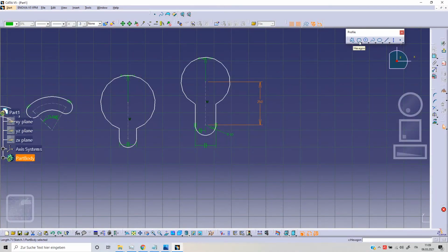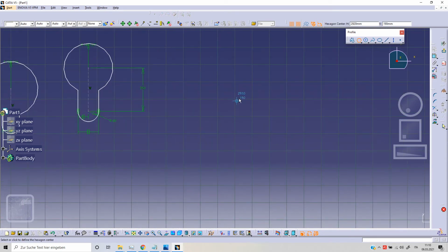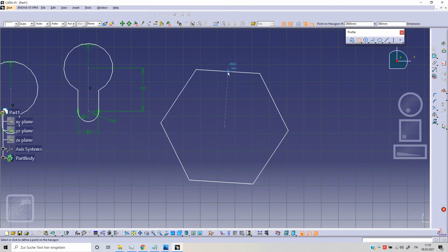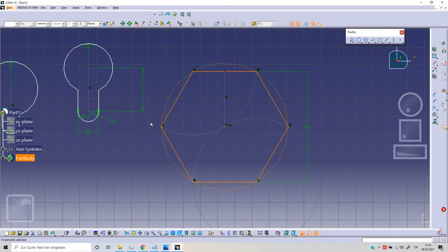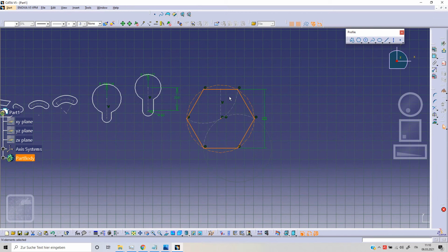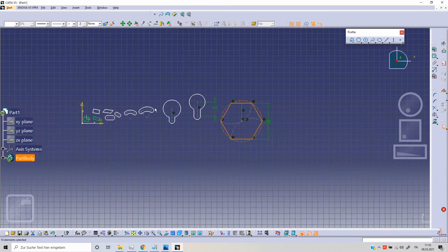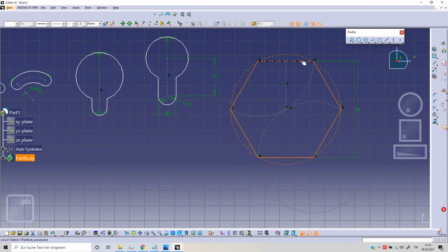Next option is Hexagon. With our first click, we fix the position of our center, and then we can select the orientation, as you can see here, but we can select even the length of this segment. As you can see, we got our hexagon inscribed in a circle. Normally we will use conditions like parallels. For example, we should impose that this segment must be parallel to another segment, or normally we will use this parallel or horizontal or vertical. This could be the best way to use our hexagon.